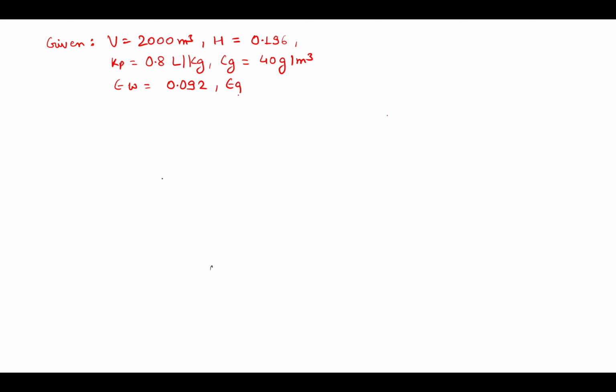Gas porosity is given as 0.3, and the bulk density of soil is given as 1650 kg per meter cube. So we can convert it into kg per liter. So it will be 1.65 kg per liter. So when there will be no NAPL, the expression used to find out the total mass of the contaminant is